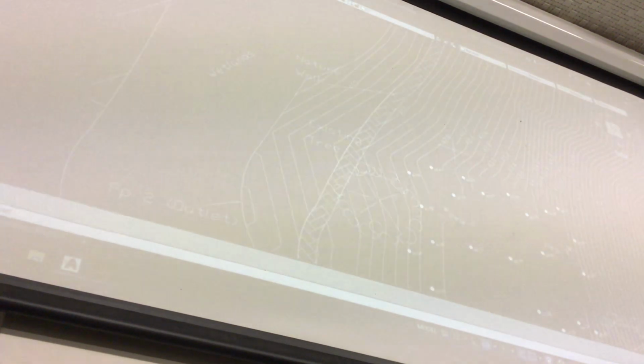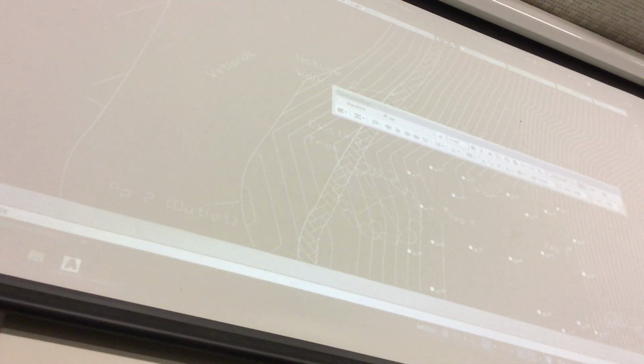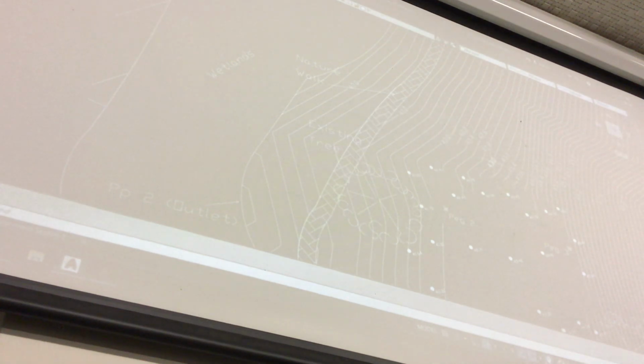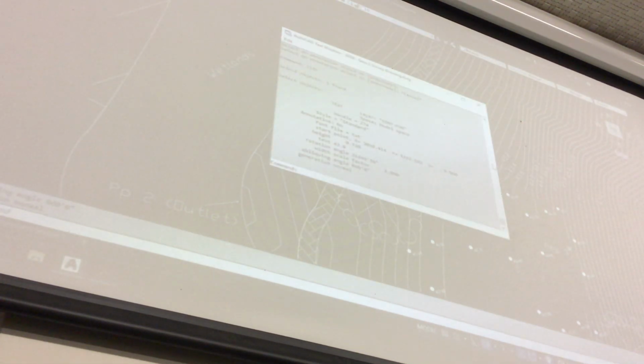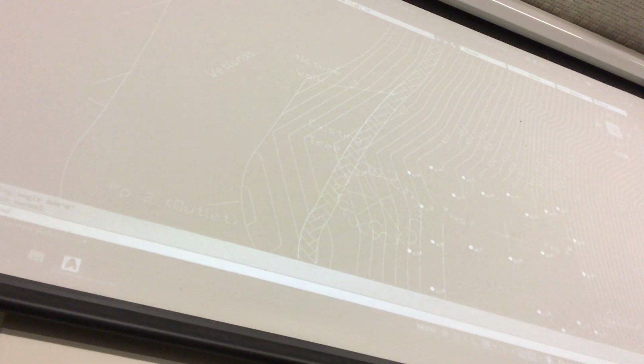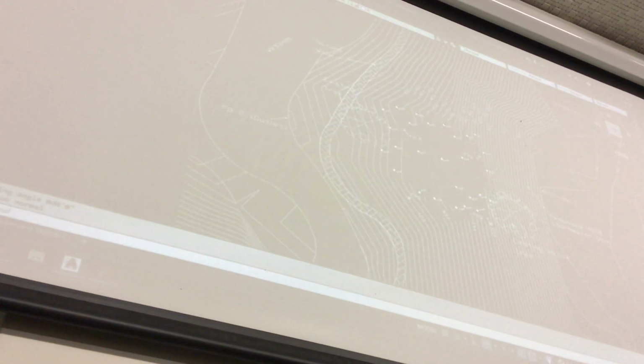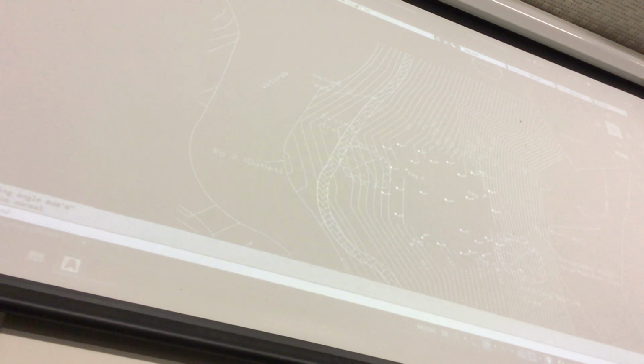There's text on here already, but when you do your calculations, you're going to find that text height of 0.360 is wrong, and a text height here of, can I even see what that is? I'll list it. 43 is also wrong. So the text heights are completely wrong that are on the drawing. Please don't use those text heights. I'll give you an example over here of how to change text heights cleverly.